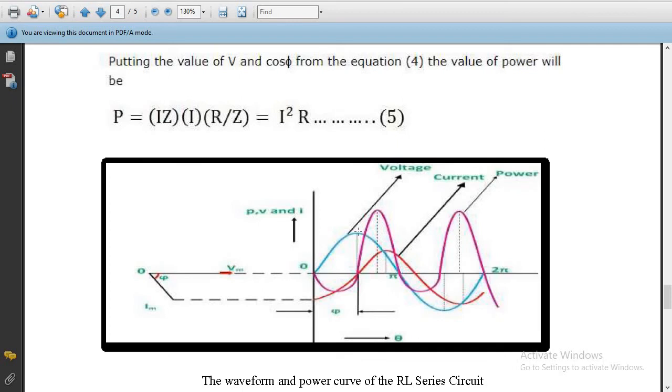Okay, so that is why the phase difference is 90 degrees. Then we just go on like this. You can see the power peak like this. Why is it like this? Because it is VRMS into IRMS into cos phi, right? The power peak is very small over here. You can see the voltage in this region is this, and the current in this region is this. So the product multiplied by cos phi is going to come like this.